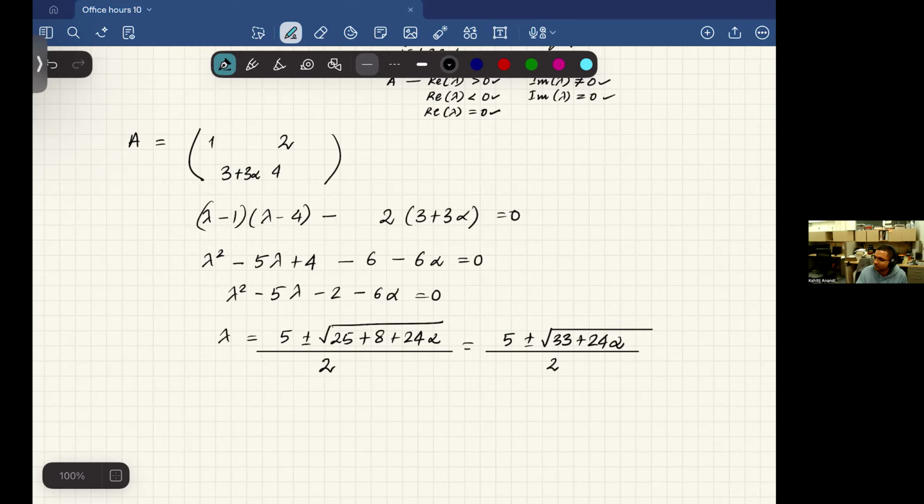So the same thing is going to happen in the 4 by 4 system. In the 4 by 4 system, you will have 16 entries. Some of the entries will have H beta in them. When you go ahead and write down the characteristic equation, you will get that the four eigenvalues are dependent on the value of H beta. And then you have to comment on why, if I have a hugely negative H beta, the real part of all the eigenvalues is going to be positive, which means that the system is going to get destabilized. Does that help? Yeah. Perfect.